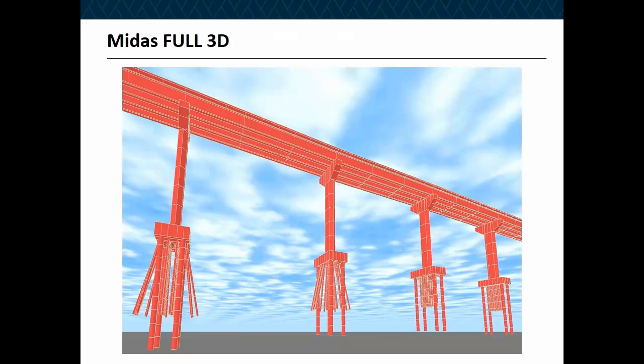So this is the schematic view of the bridge. This is a rendering that I've done with Midas, full 3D option in Midas. You can see the superstructure is composed of a composite deck, including the pre-stress post-tension beams, supported on hexagonal columns. Like I said, massive pile cap, including this photo, which is from the rendering of the Midas, shows the pile caps, including existing piles and retrofitted piles.